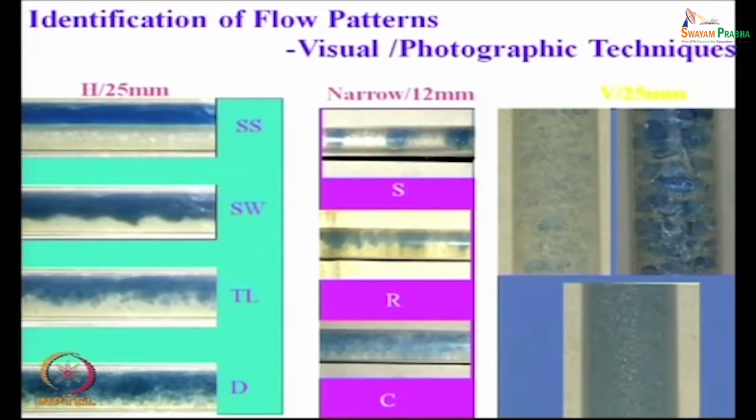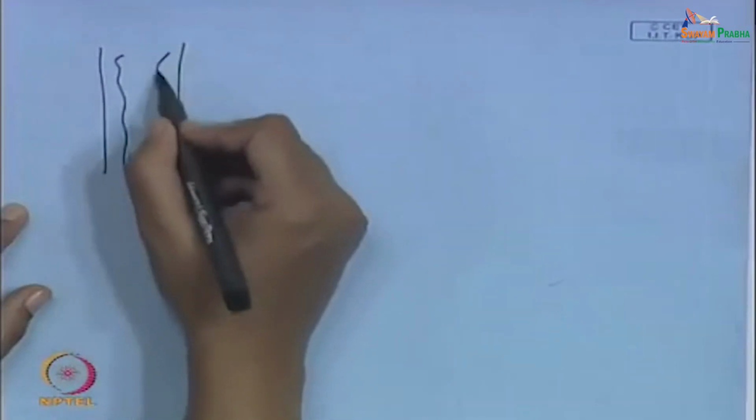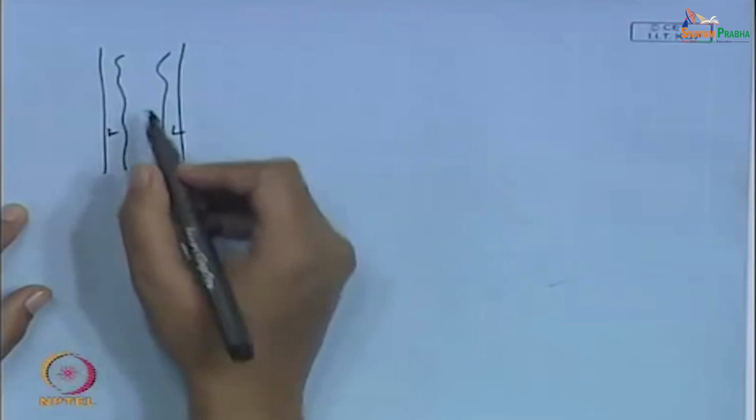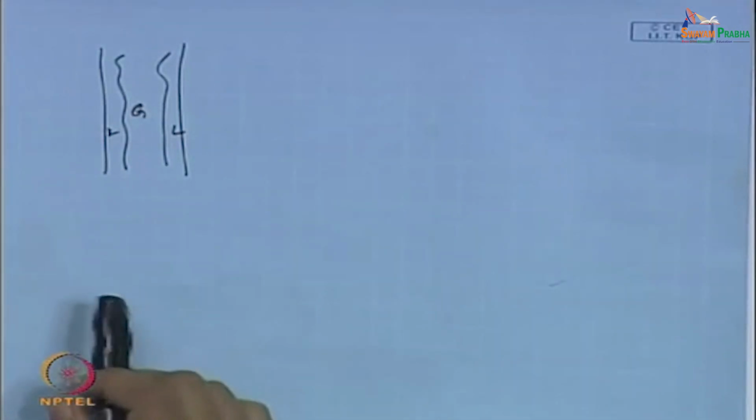The fourth difference, as I had already mentioned in the last class, is that either of the phases can wet the pipe wall. For air water or vapor liquid cases, when we had a very high gas and a very low liquid flow, we had the annular flow pattern, where there was a thin liquid film and a continuous gas core. Beyond this, we did not have anything.